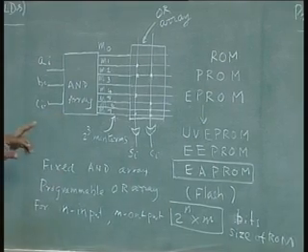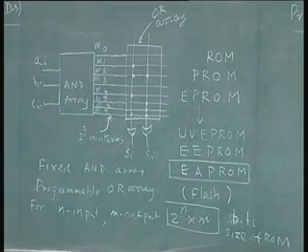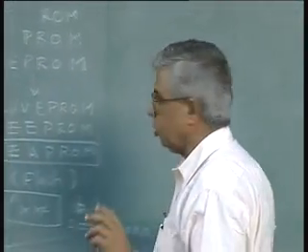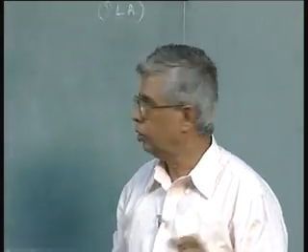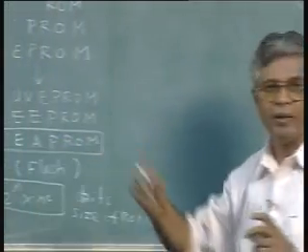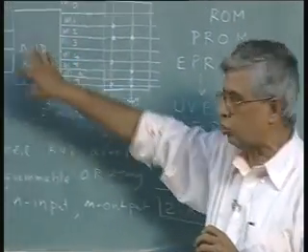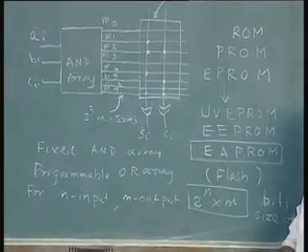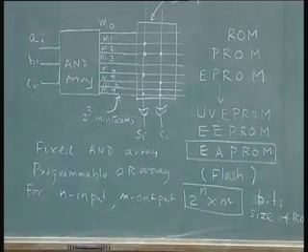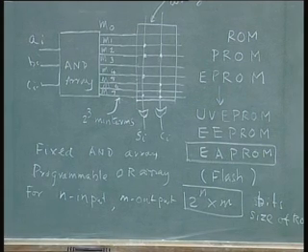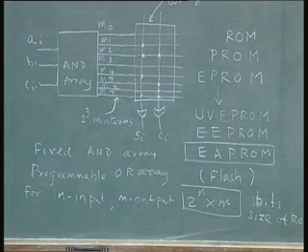But in the programmable logic array case, I will use a few select product terms in order to generate the required output. That means I do not have to have a whole set of 2 power n AND gates. I will have a fewer number of AND gates and generate a bunch of product terms which will be used in the implementation of the final output.